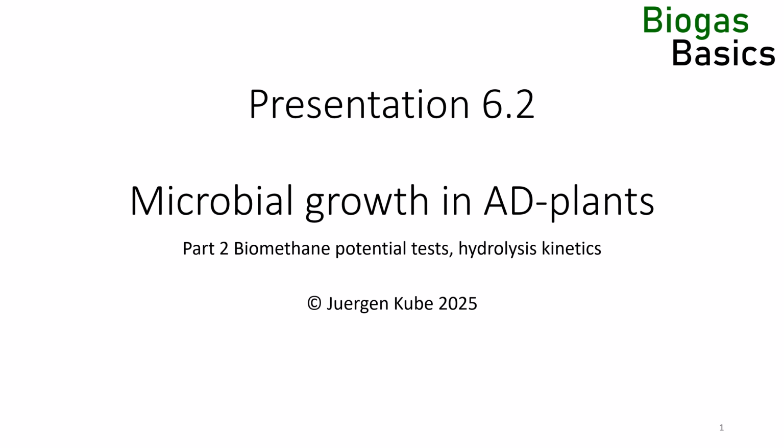In the last presentation, we looked into the basics of microbial growth, why it's called exponential growth, how the doubling time of microorganisms is linked to the hydraulic residence time in a continuous steady-state culture, and we investigated the simplest substrate biomass model with a Monod kinetic. We distinguished washout point, turbidostat, and chemostat regions, all very theoretical.